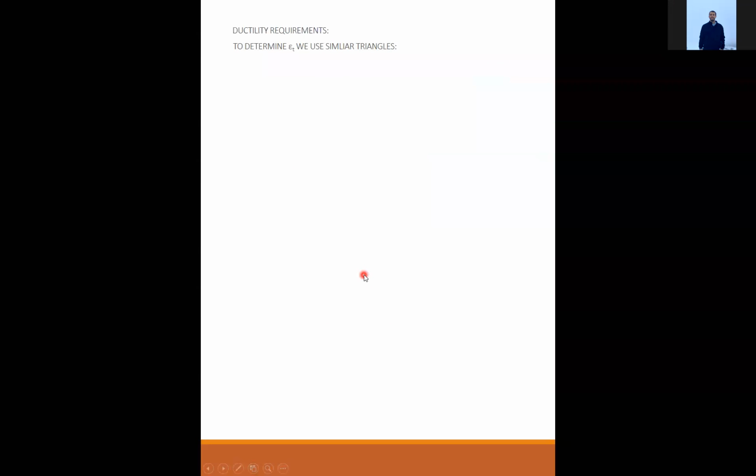Professor, what again does 0.005 represent? It's a threshold. Normal 60 KSI steel yields at 0.0207. So somebody decided we're not going to set that number right at 0.0207. We're going to have a safety factor in there. So somebody just decided, you know what, let's make it 0.005. That sounds safe. And that's just a number that the code committee came up with that we must abide by.